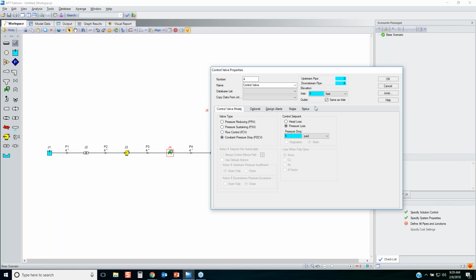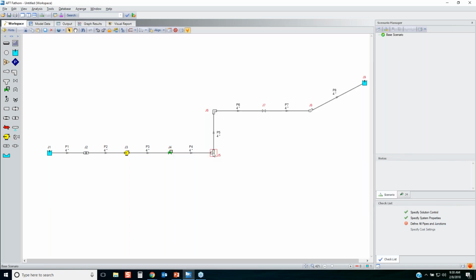And I want to make sure that if I did have a real control valve, I want to be able to maintain at least a minimum pressure drop of 5 psi at my desired flow rate. That way, whatever control valve I might select, it would be able to have good controllability for its lifetime. And so that's how I'm going to model my control valve right now.